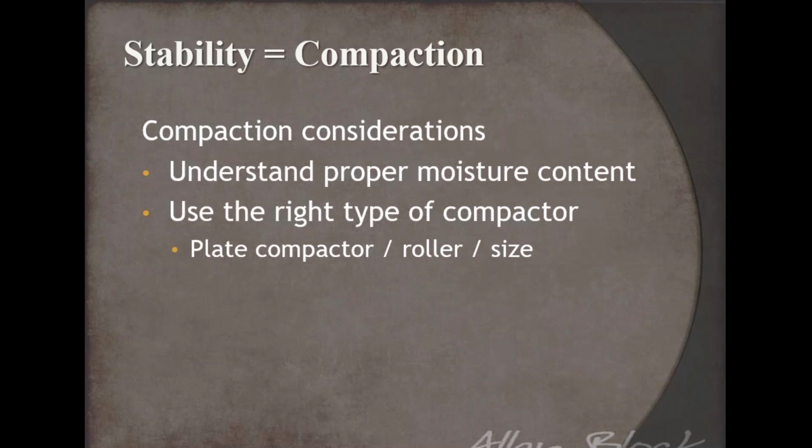But then over time, if you add a little bit too much water, the sand's just going to run away. So there's that sweet spot for that sand. And then obviously, when it comes to compaction, it's the level of effort. It's the loading that's being applied to it. So using the right compactor is important too.